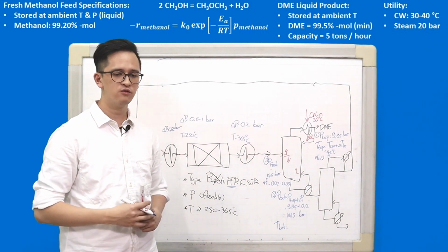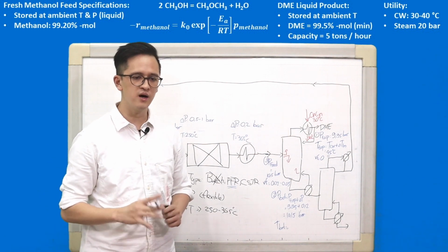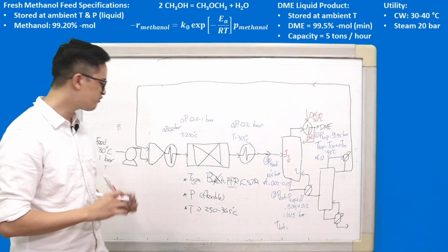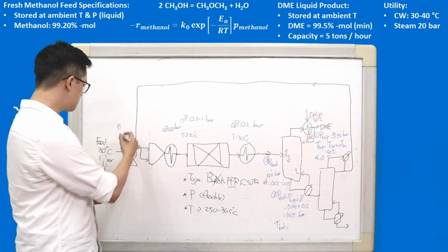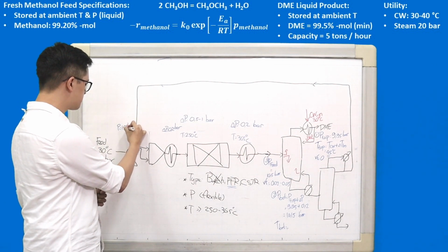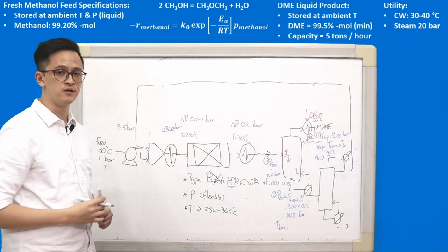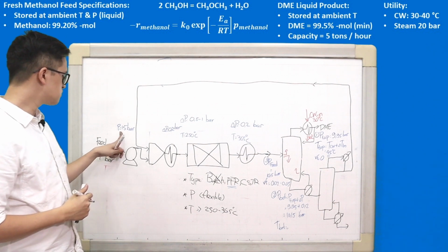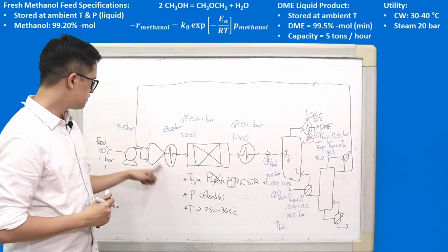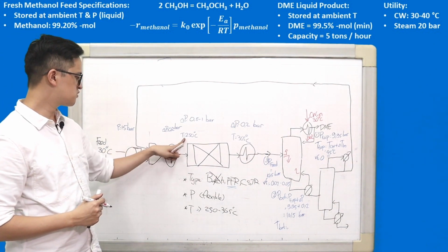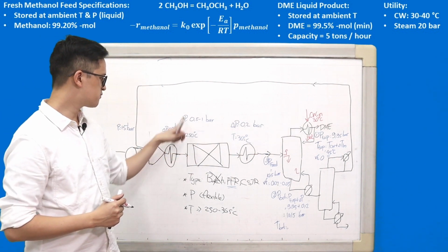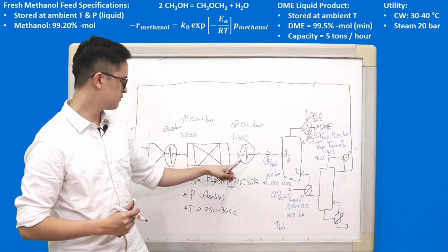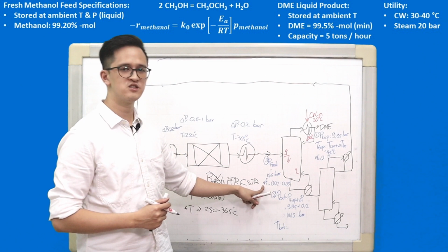That means we have to provide another 1.2 bar, roughly. So from those 12 bar, I'm just going to round the number to 15 bar, just as a starting point. Okay, so it's done. Delta P is provided, temperature is provided, pressure is provided, vapor fraction is provided.